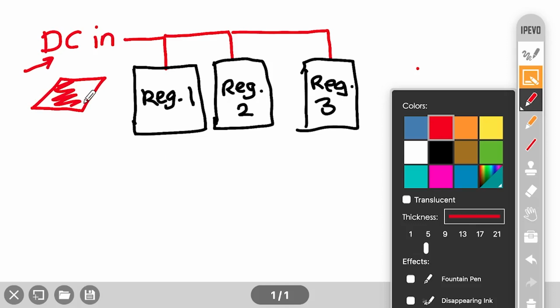This is also something that's required in high-speed PCB design. The output lines could be routed as traces or you might want to use an additional power plane if each section carries high current.